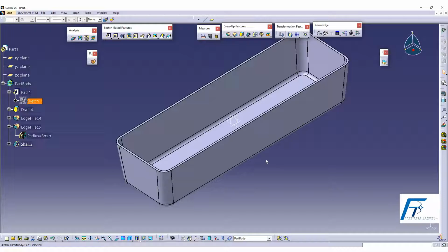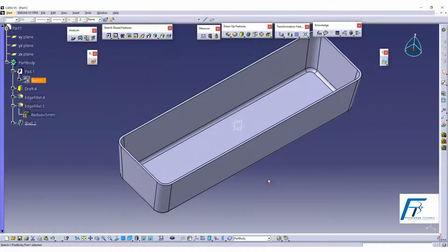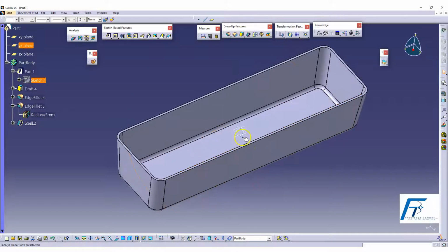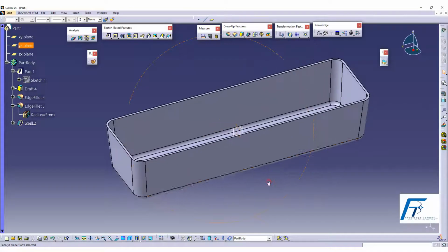To create a stiffener we need to have planes. In this case, I would like to create a stiffener at each and every location. I'd like to create a stiffener here, here, and here, to increase the strength and in line with the fillet that was created. So let's get into that. For creating them I need certain reference elements, because you have only one plane, this particular plane. So I'm going to create a reference plane.